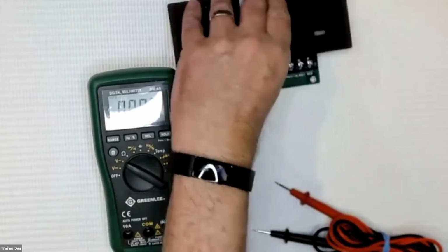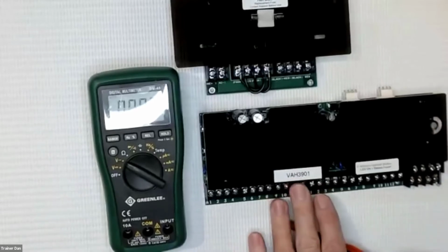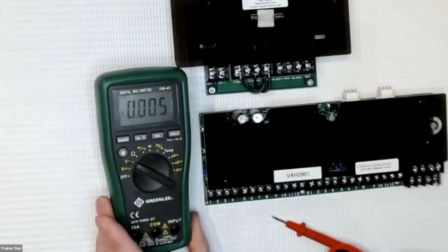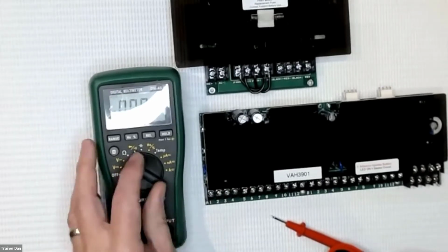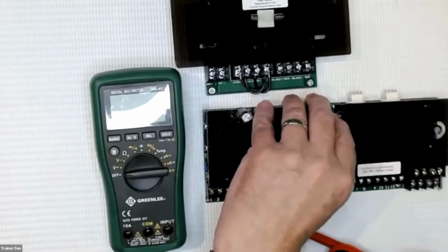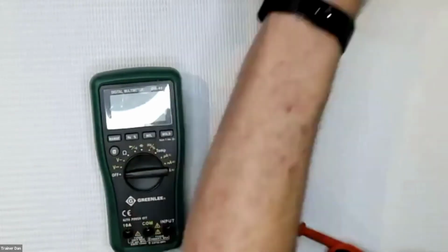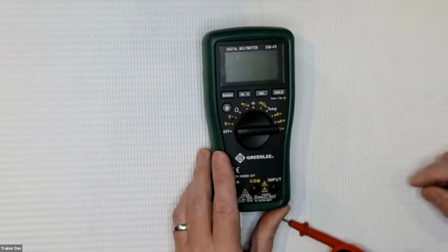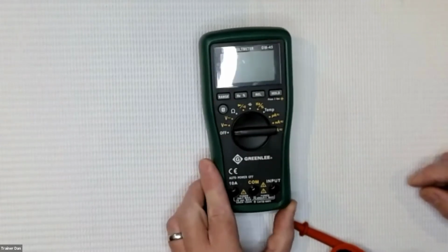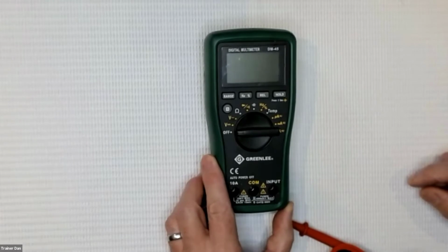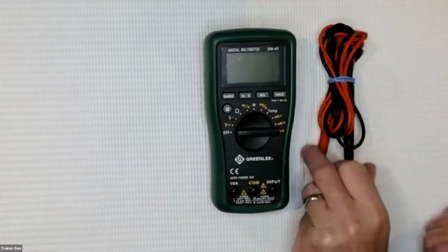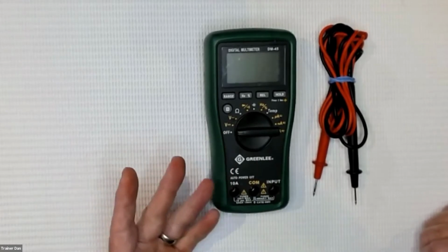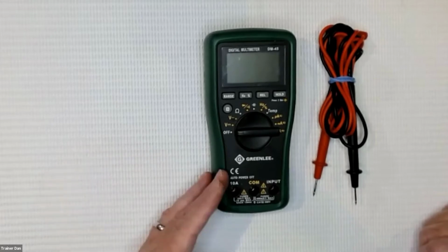Or let's say we were doing conventional wire. I could do that exact same thing, testing on that conventional wire board. So a volt ohm meter is great. You can also use it for resistance to see if you have a complete circuit, and find out how your wire path looks, or any portion of your wire path. A volt ohm meter, I think, is the basic entry tool into doing any irrigation troubleshooting. I cut my teeth using these when I spent most of my time originally on conventional wire systems. You can get these from anywhere from $10 to $200, maybe even more.